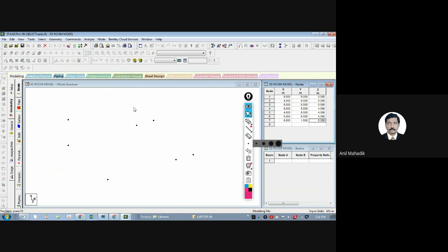Now putting all these coordinates is a really time consuming task and very laborious task. So there has to be a shortcut. So when the model becomes of large size, then this method is really not suggested. That putting all the coordinates, measure all the coordinates, and then put these numbers here. So we can have a shortcut for this. So instead of this, we can replicate the nodes.